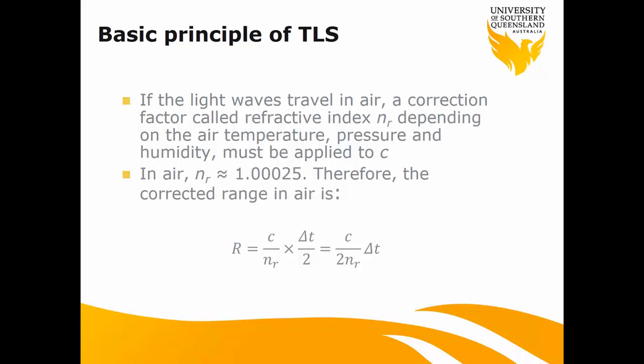Air is a medium. From Survey A or other courses on EDM, we know the laser beam traveling in the air will be affected by temperature, pressure, and humidity. That means we have to consider the effects of the refractive index.